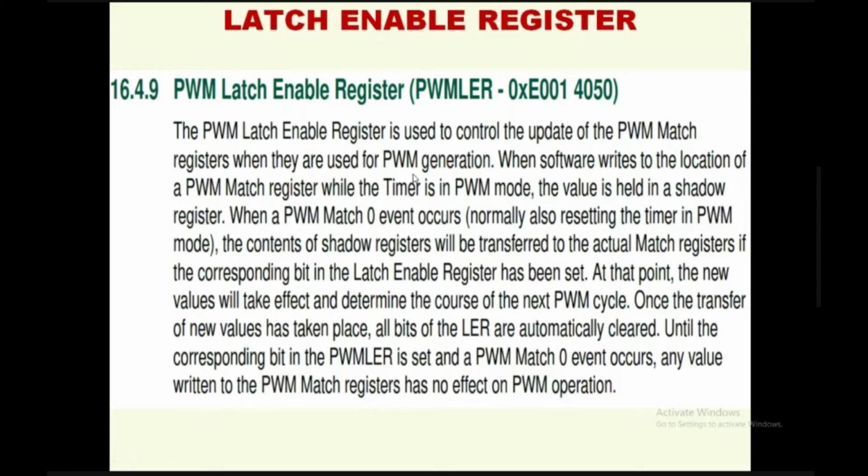Now, what value will be kept in MR5? It will be in the shadow register. Whenever the PWM match 0 event occurs after one period, right? After one period, the content of the shadow register will be transferred to the actual match registers if the corresponding bit in the latch enable register has been set. Okay, so when we set the corresponding bit in the latch enable register, the content of the shadow register will be updated to the match register after one period.